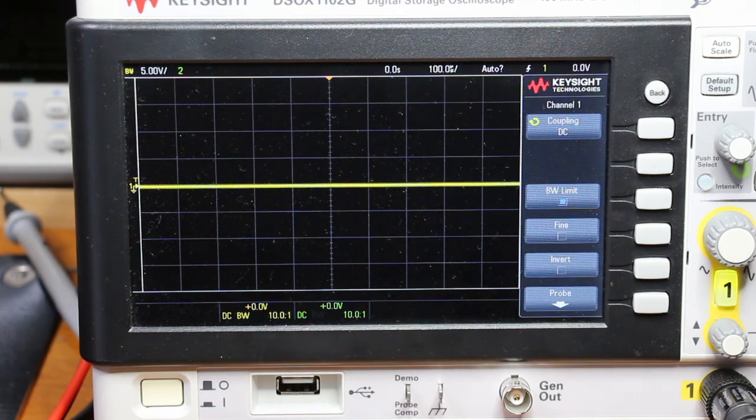The noise test shown in the first video, video 34, was made by switching the filter at the input of the oscilloscope on and off, this filter here. And the reason is that when we measure the output noise of switching power supplies, theoretically, when we insert the filter, we are measuring just the ripple. And when we use the full bandwidth of the scope, we are measuring ripple plus transient.